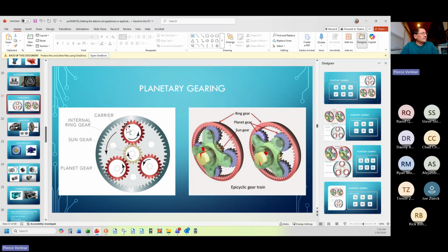And what that means is you now have less torque transmission capability, which means you have to derate the box as you go up in ratios because the planet gears get smaller. And I find that the point of diminishing returns is around 8-1. You go to 10-1, you have to derate too much. However, many people sell 10-1 planetary gearboxes. So don't just take my word for it. You have to do the numbers. In general, I've typically gone to 2 stages when I go beyond 8-1.